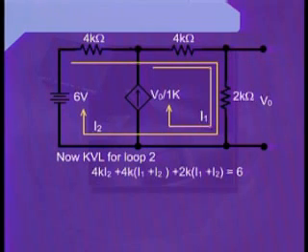Therefore, we can move to the next 2 kilo ohm value, which is connected across the output terminals of the circuit. Therefore, we write plus 2K, and once again we can observe that there are two currents, that is the current I1 and the current I2, which are passing through this resistance. Hence, we can write I1 plus I2. We have summed them up as well in this case, because both the currents in this case are also flowing into the same direction.